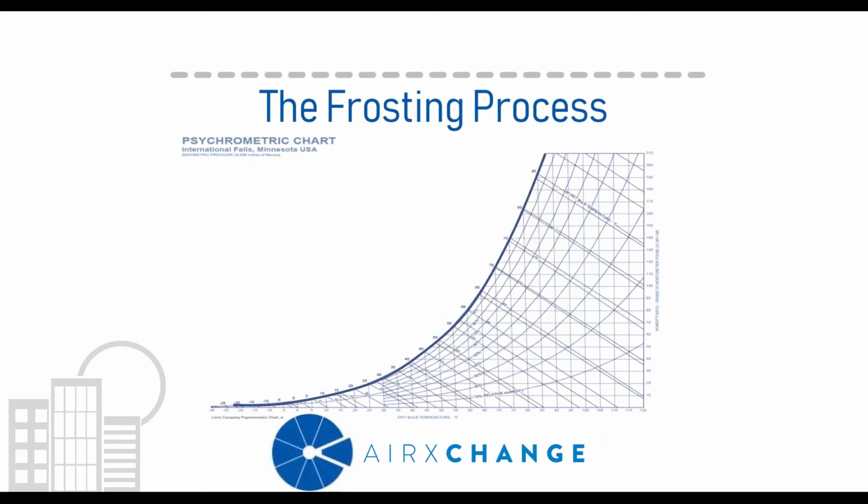The top curved line represents when the air is completely saturated. This means that the air can't hold any more water. I'm going to refer to this as the saturation line or the saturation curve. Remember that when air has reached this point of the process, the air has reached 100% relative humidity. That means it simply cannot hold any more water vapor.